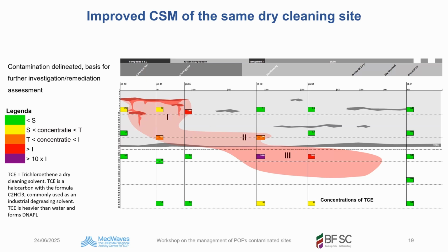Yeah. But you missed the first question. Yeah, the first question, there are many CSMs. Numerous. I mean, there are no sites alike. Every site is different, so a site-specific approach is important. But of course, if you have a fuel station and you have made site investigations on 10 fuel stations, you know more or less what you can expect. But still, the situation will be different. And that is, of course, the experience you have. When I'm going to a large depot for fuel, I know where to look: filling points, ventilation pipes, and so on. So experience is also a very nice tool to have to do the site assessment.